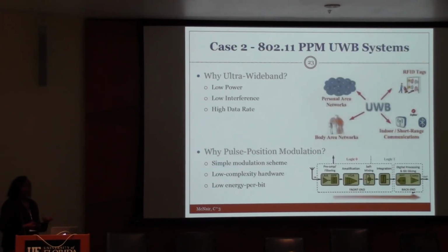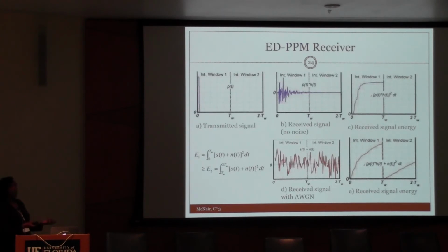The other adaptation we looked at for these small, closely located ad hoc systems was to look at some of the existing protocols that maybe can be updated to consider environmental information and behave differently in normal operation, adjusting different parameters. This one is for an ad hoc network of small devices that operate using ultra-wideband. We looked at the problem of pulse position modulation, where you receive a pulse in a given transmission window and declare whether it's a 0 or 1 based on its position. It's a very simple scheme, low complexity. How can we adapt that to what we might want to do in the environment?